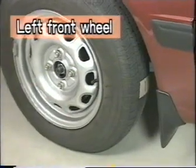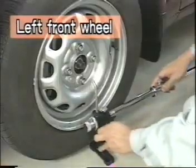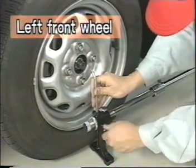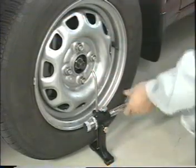Put a mark in the center of the tread on the rear of each front tire and measure the distance between the marks. The mark should be made at the same height as the spindle.